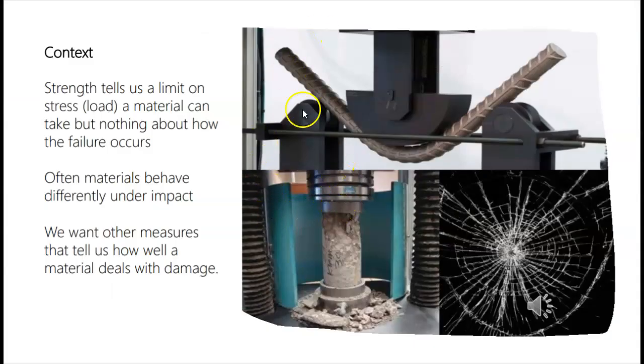Now, if you want to test a material, we can do compression or tension, or we can do a bend test. Depending on the material properties, the material can be either strong or weak. If the same material has a higher tensile strength, it doesn't mean that it has exactly the same compressive strength.